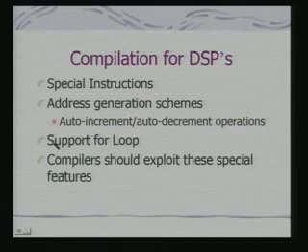Another interesting feature is address generation schemes. Many of these DSPs provide support for auto increment and auto decrement operations. In fact, your general purpose processor like ARM also provides this feature. In fact, ARM in various ways does incorporate DSP features. Then there is support for loop, what is called zero overhead loop. That support is there in the hardware, and the compiler therefore should exploit these special features. We shall see how these special features can be really exploited.